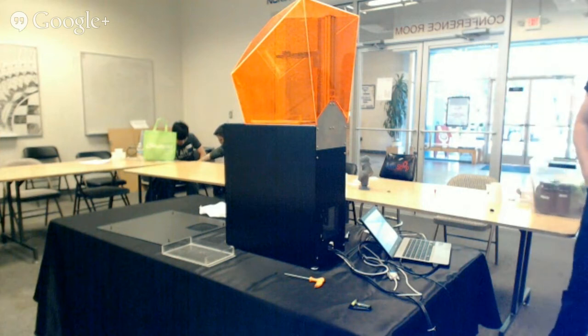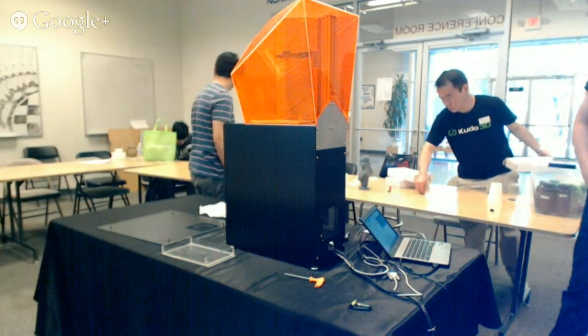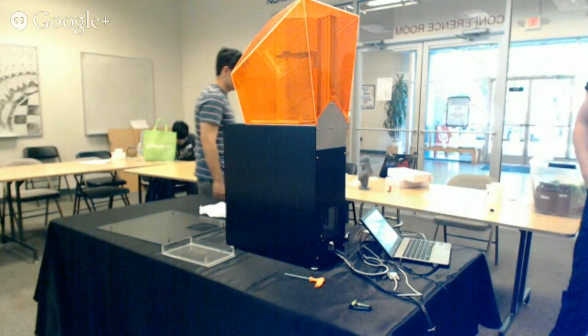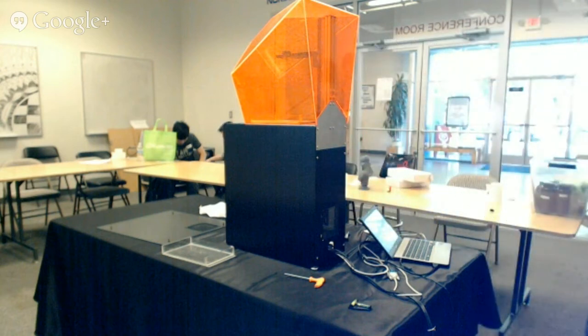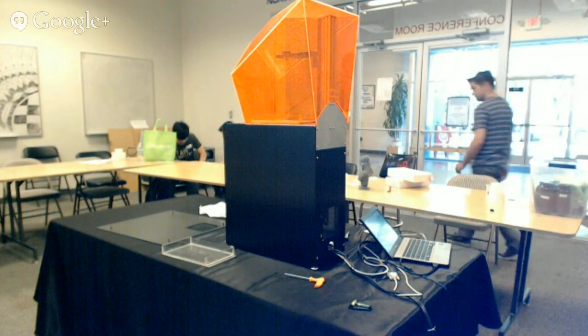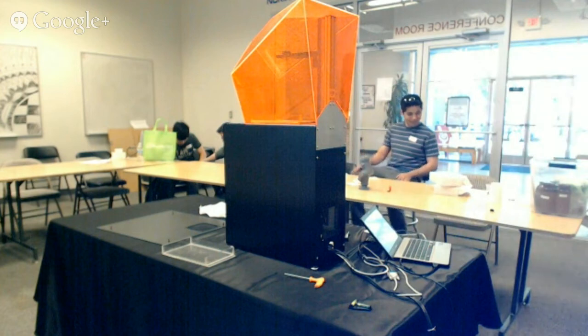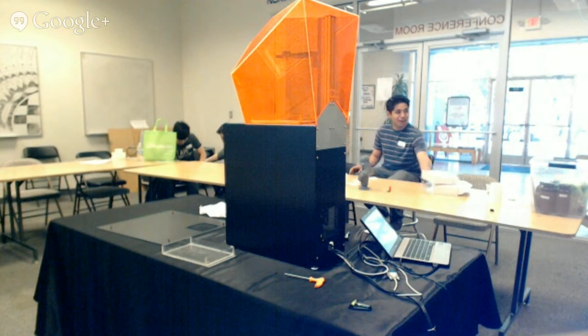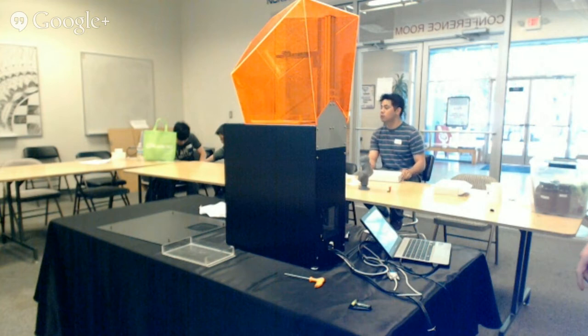If you've got new resin that no one's ever used, exposures may often change depending on the shape of your part too. You may need more or less exposure depending on the properties you need. Less exposure does make it easier to lift, but increases the chance of warping. So if I need a really straight part, I need to cure it more. Sometimes substantially. In order to get this part good and flat, I had to go up from 4 seconds to 14 seconds per layer. So even that would curve otherwise?